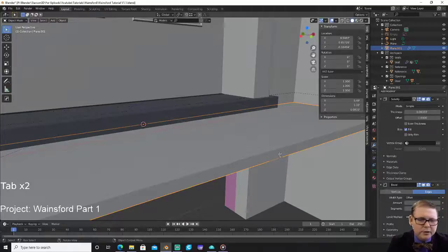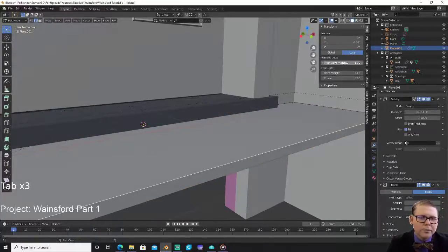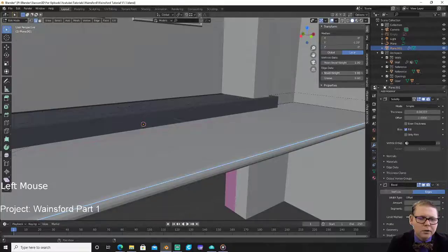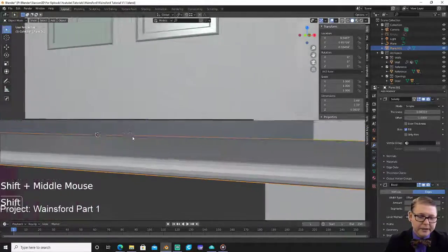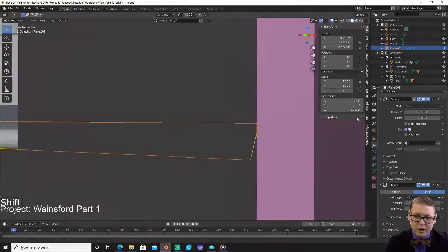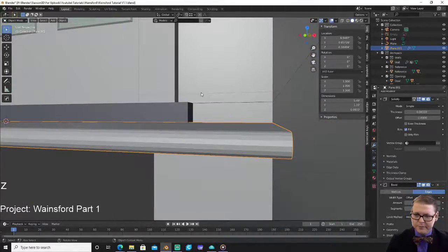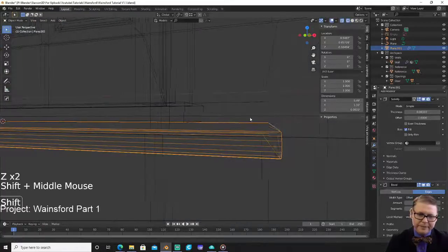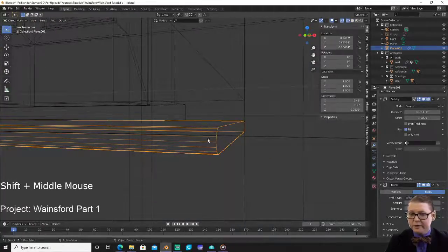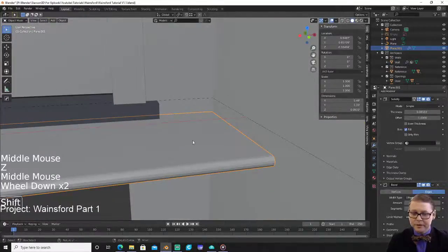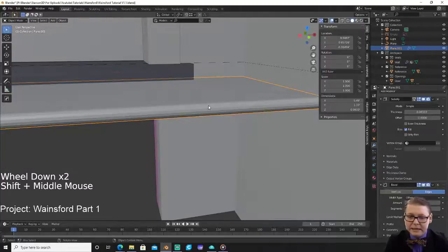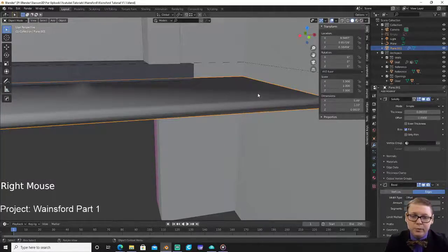it is not actually mean bevel weight. Oh, here we go. Instead of mean bevel weight, we just click on bevel weight. I clicked the wrong thing. Anyway, so now the sides of our tread are still flat. Maybe if I go into wireframe, you can see it a little better. Yeah, the edges over here are still flat, and it's just the front that has that kind of bullnose. And then if we want that to be a little bit cleaner, we can go to Shade Smooth.